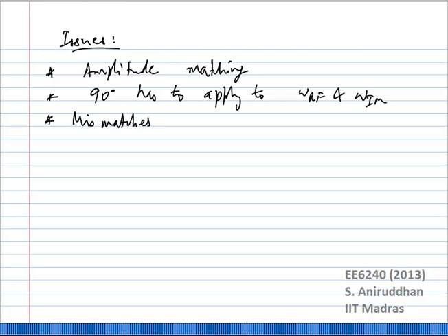Okay? So, to do this, you will actually have to assume that there is some amplitude and phase mismatch between the two parts. So what I'll do is I will not go through the math. You can assume that the LO inputs are mismatched. You can combine all the amplitude and phase mismatches on either side and draw them into the LO.